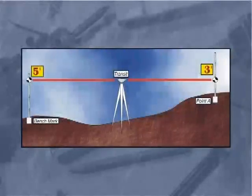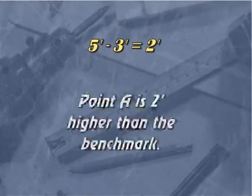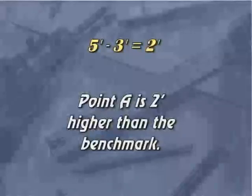Now, what we're trying to find out is the height of point A. When we turn our transit over and read the stick over at point A, it reads, for example, 3 feet. We do a little bit of math. We take 5 and subtract 3. That would indicate to us that point A is 2 feet higher than our benchmark. And then we would go around the site continuing to do that and continuing to mark. That is what basically leveling is all about.